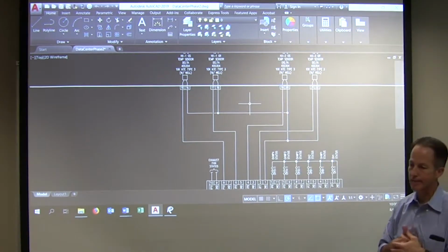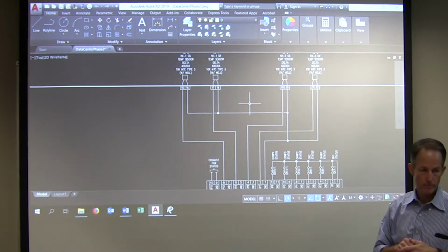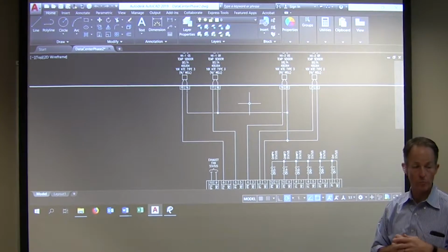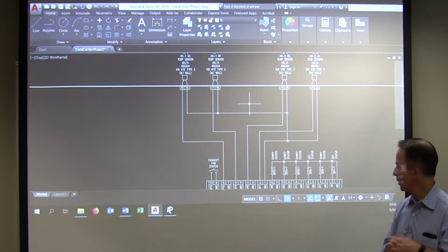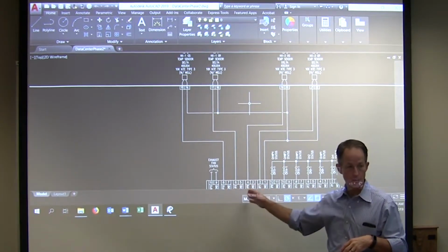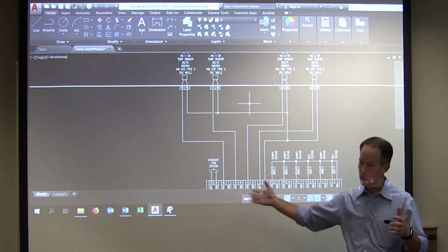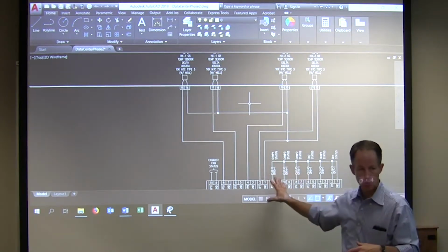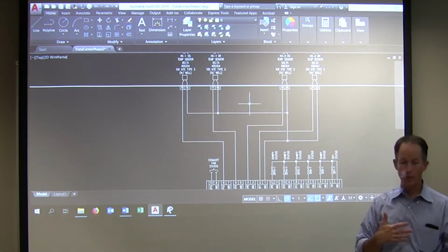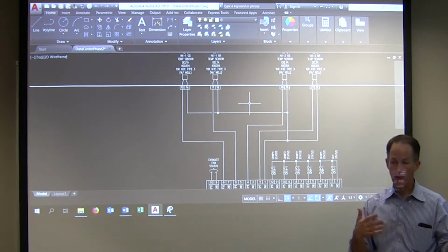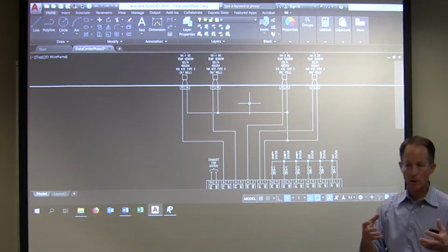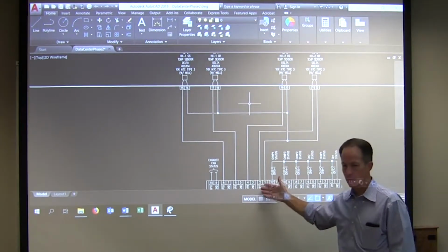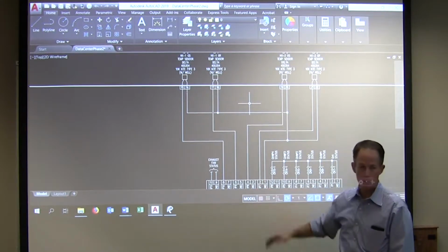What are my options then? If everything's good from there, then you've got something internally inside of the board. So the controller is probably where the problem is. Now, if I have an available input next to it, that's my next step, right? Try another input. If I can't set up the controller to do that, get help from our controls group, or have them come show you how to do it. The more we learn, the quicker we can get through some of this troubleshooting, the better. So try another input. If that still doesn't work, could be the board, right?